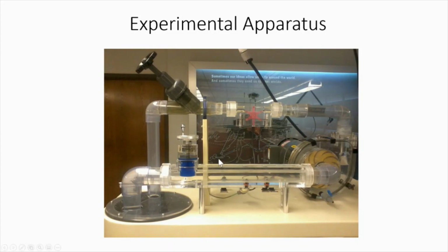Now, how can you induce cavitation in the system? Well, with the similar equation, you reduce your NPSHA and NPSHR margin. So you have to reduce the available pressure in your system. How can you do it? You can induce friction. One way to do it is using a rough pipe, making it longer, reducing the diameter. But that's not modular.